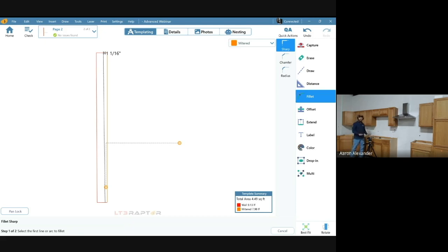Obviously, if we have our laser at this height and we try to aim right onto that countertop, our laser is going to be stretched out like 6 inches. It's definitely not going to work. Not recommended, right? So I'm going to take 2 of these blocks here, and I know that line's a 1/2 inch off the bottom. So I'm going to set one up on the actual countertop. If I was running all the way over here, I'd set it on the countertop here with that line a 1/2 inch up. And then I'd set the other one down here on the countertop with that line a 1/2 inch up.